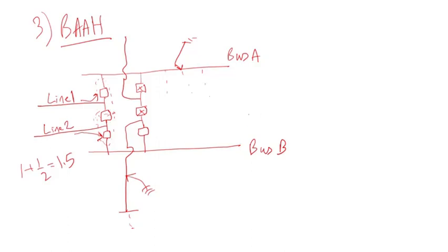So with 4 facilities or lines connected, the worst case, you will lose 2 if this middle breaker fails to open. Which is still better than a straight bus.